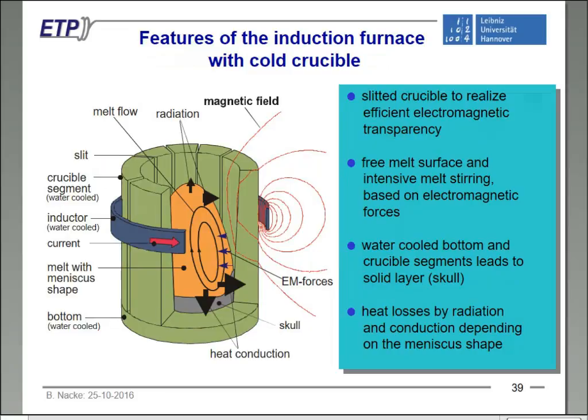So, therefore, time is running, I want to leave the conventional furnace and come shortly to the cold crucible technique, first the technique for melting metals and alloys of metals. If it is not possible to use a ceramic crucible for melting high-performance materials, or if the melt is so reactive that it will destroy the ceramic lining, we can use a water-cooled crucible.